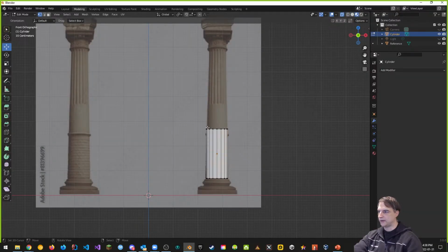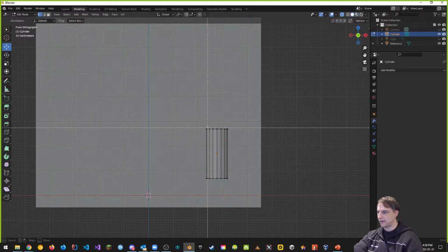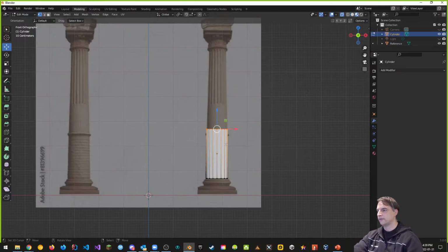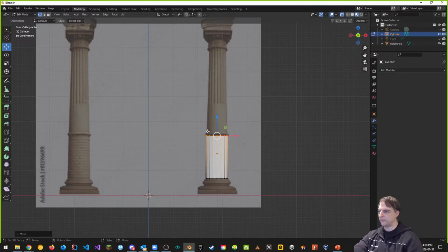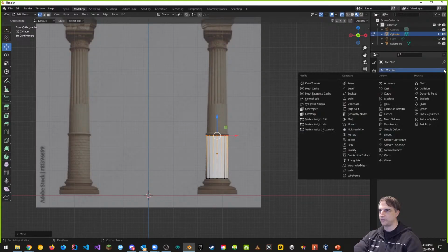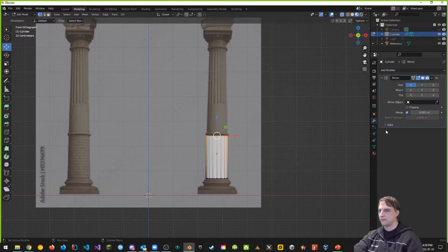So let's suppose I want to do that now. What I can do is grab the top vertices here, just those top ones, shift back into this viewport shading, and then scroll down so I can hit this part right here. Good. Now that I'm going to do this part here, what I want to do is start the mirroring modifier. You can add the mirror modifier anywhere, but you can only apply it during object mode. So again, I'm going to go into mirror. Here's the mirror. And notice the mirror that I'm adding in,